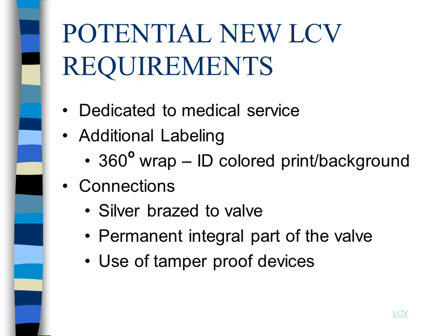There are numerous examples, and some of them are very catastrophic. They've been very deadly. There are numerous examples where a maintenance person or a driver couldn't get a vessel to hook up to a manifold, so he took the fittings off of the empty vessel, swapped them out with the full vessel, and hooked the full vessel up to the manifold.